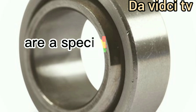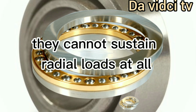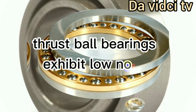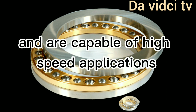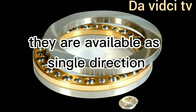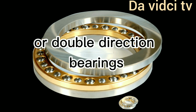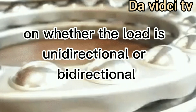Thrust ball bearings are a special type of ball bearings designed specifically for axial loads. They cannot sustain radial loads at all. Thrust ball bearings exhibit low noise, smooth operation, and are capable of high-speed applications. They are available as single-direction or double-direction bearings, and the selection relies on whether the load is unidirectional or bidirectional.